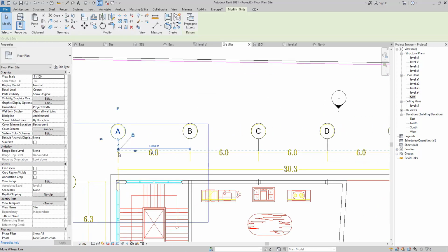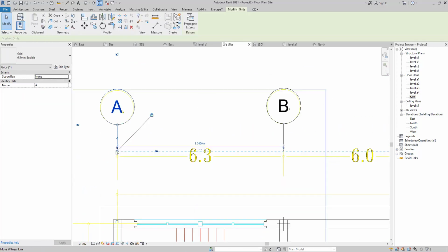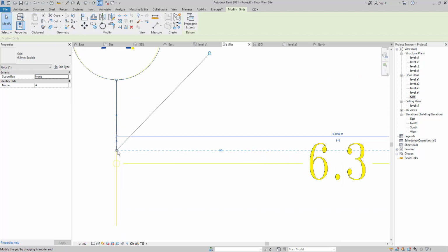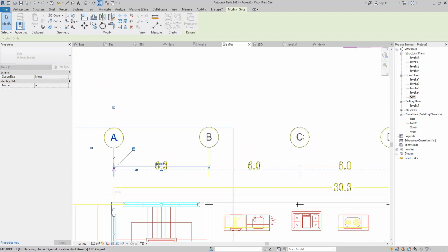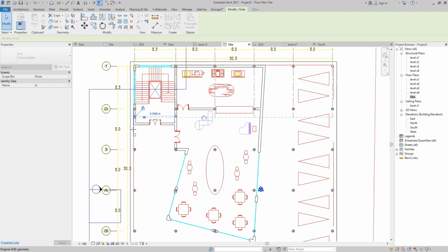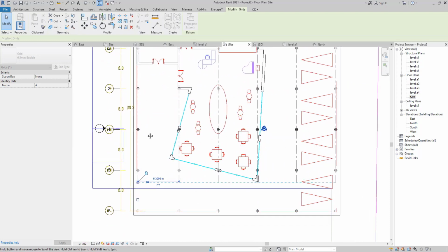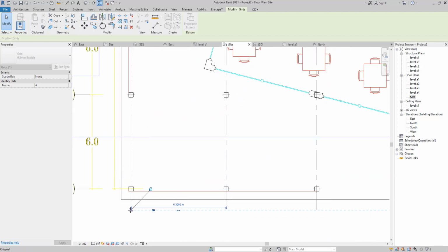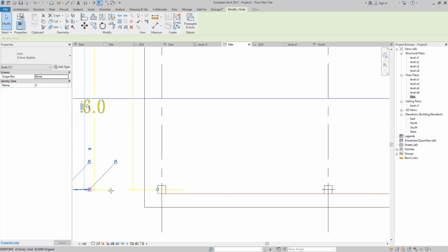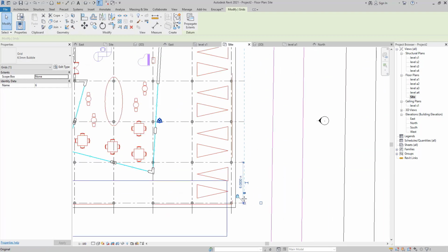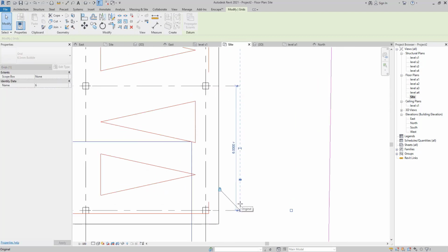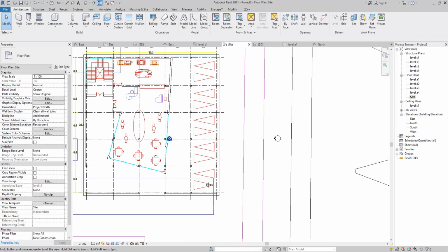The next step is to grab one of them, and it's very easy. We just click on this circle and take it down. All of them will automatically move with each other. We don't need to even worry about moving one by one, because Revit takes responsibility to do all of the easy operations. So far we created our grid.